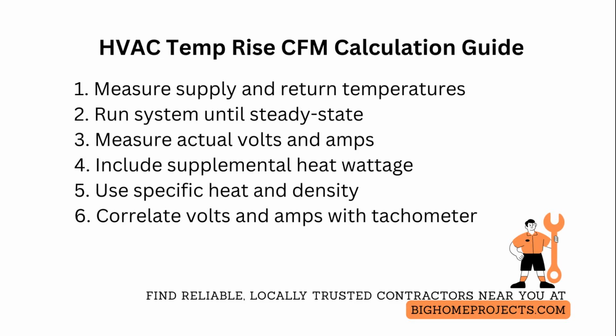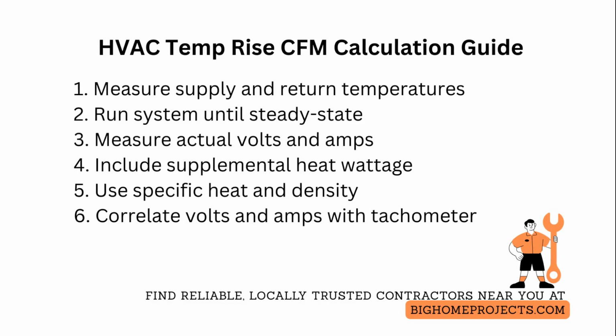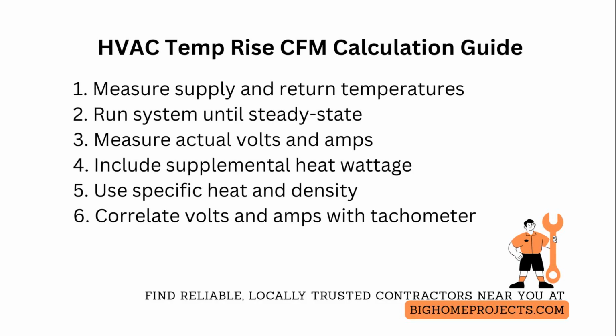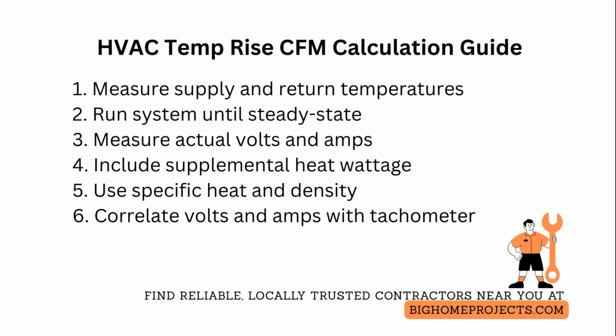Convert measured volts and amps into input watts using measured volts times measured amps times the motor power factor if you can measure it. If not, use a conservatively tested power factor value from the motor nameplate testing or motor manufacturer data to avoid underestimating heater wattage.